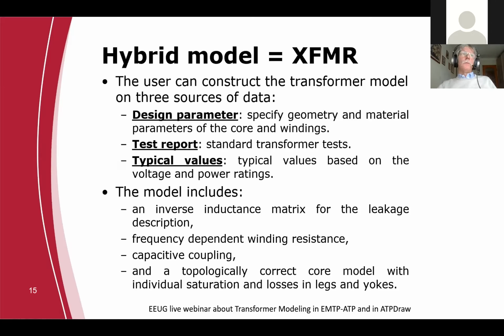Sometimes we are not informed about the capacitance of a wind farm transformer, because this information is not there in the transformer manufacturer datasheet or manufacturer test report. So it's very useful to use typical values in that case, because it is sometimes very dangerous if you omit the capacitances, especially if you have a delta connected winding without any connection to the ground reference. The model can produce quite unusual behavior.